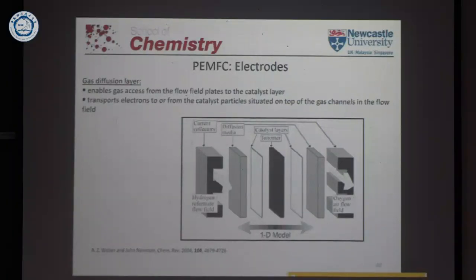and Nafion in fact shows a number of really advantageous properties for that conduction process, which means high conductivity, and a good separation of the gases from the two sides. Here on the one side you have hydrogen, on the other side you have oxygen, and the diffusion rate across the membrane should be rather small, so that you don't have a reaction of hydrogen on this side and oxygen on that side. So then the next thing to build the fuel cell is that you need a catalyst